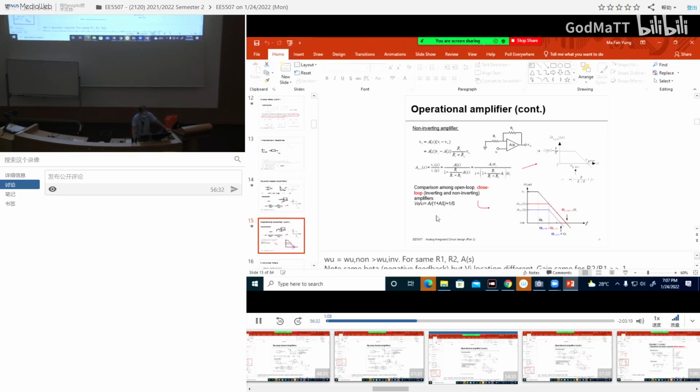And in this equation, you can see the power of feedback in stabilizing an op-amp with changing gain. So now you look at this equation: if my A is very big but not well controlled, as long as A is very big, this whole thing is approximately 1 over beta.